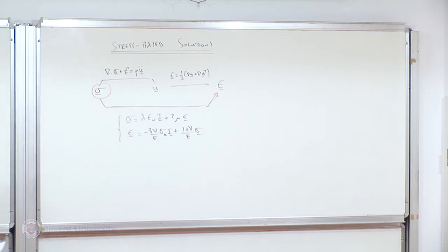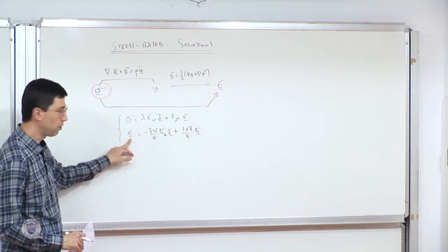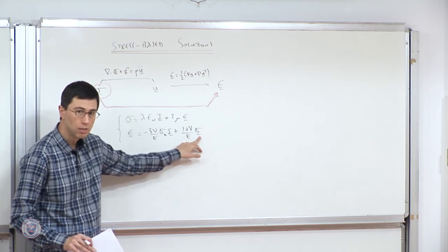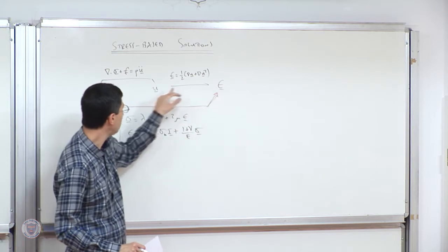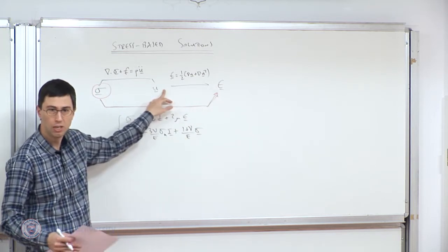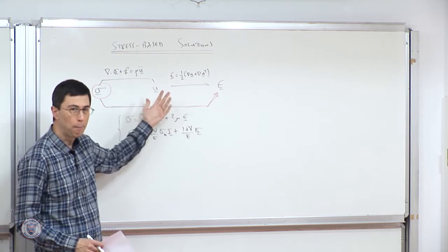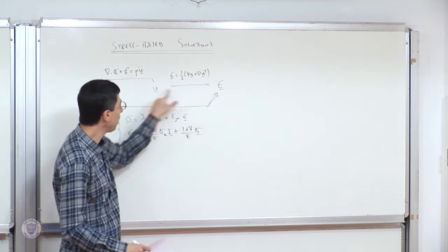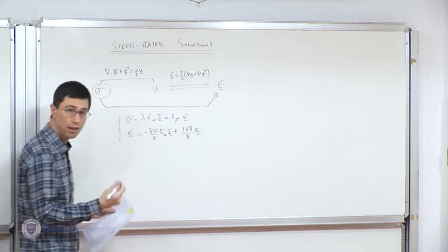So given sigma, I can calculate epsilon, but not every form of stress is a reasonable stress, because eventually I need to make sure that the resulting strain field is indeed associated with some physical displacement field, and that is ensured by compatibility, right? But does my stress through the strain satisfy compatibility? So that's something eventually that I will enforce.